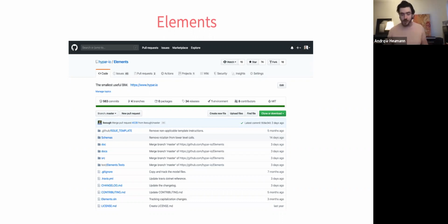For the representational piece, we looked at systems like IFC, which are great. IFC is amazing. It's this incredible standard for representing building elements in an interoperable way, but it's not lightweight and it's very hard to extend, and support for it is incomplete in even the biggest applications like Revit. The number of times I've heard, oh, this IFC element didn't translate correctly when I pulled it into Revit. This is reality, and making changes to that is often out of the hands of even competent developers working locally.